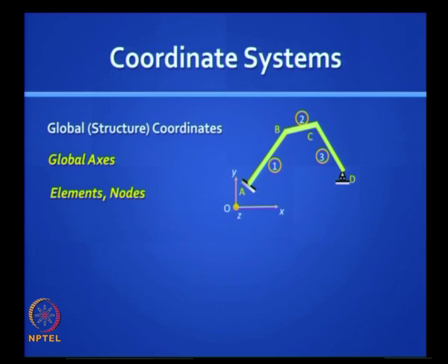So you define elements and nodes, and next you need to define degrees of freedom, right? We are primarily doing a stiffness formulation, later we will look at the flexibility formulation. So the degrees of freedom here, in this plane frame, at B and C you have 3 degrees of freedom, and let us align those along our chosen Cartesian coordinate system.